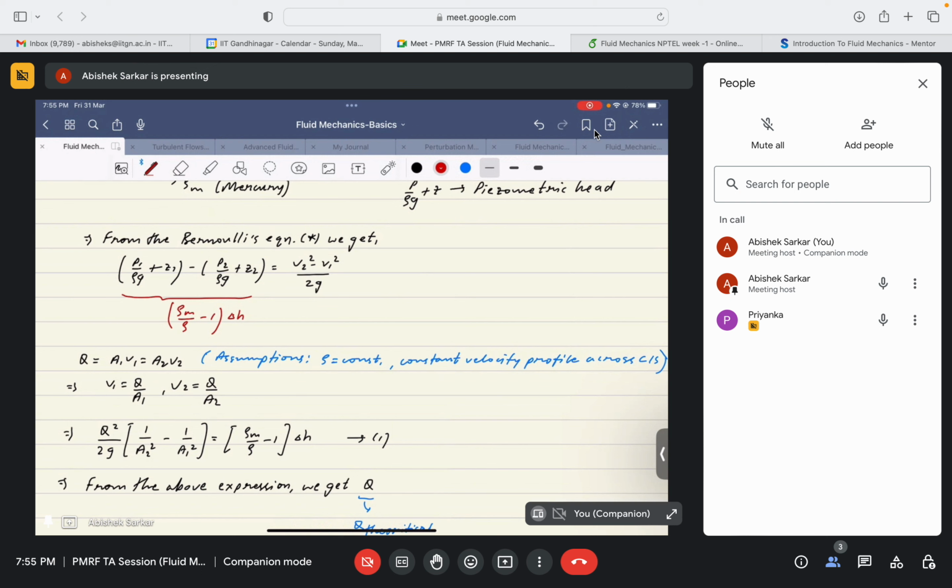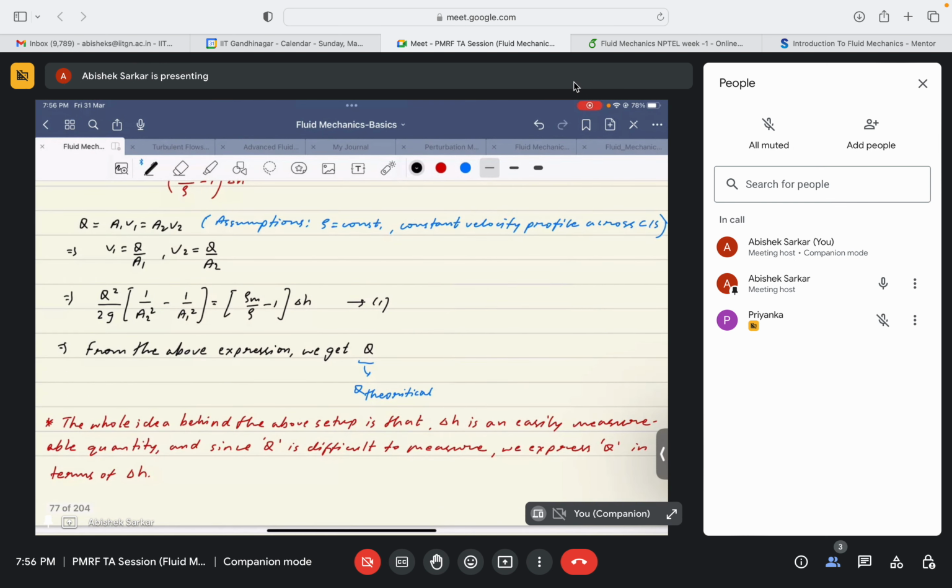Yes, sir. So viscous effects come into the picture since they reduce the effective mass flow rate and volume flow rate also. This rate term is very important because it takes into consideration the effect of time, right? So the time required for this amount of water to come out of the exit increases because of the effect of the viscosity, since it reduces the mass flow rate or the volume flow rate.